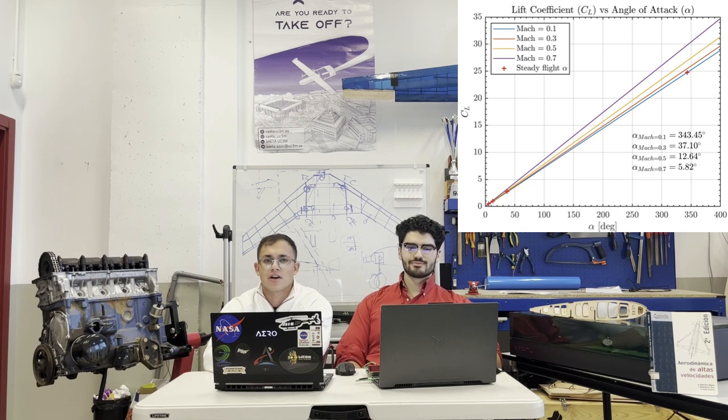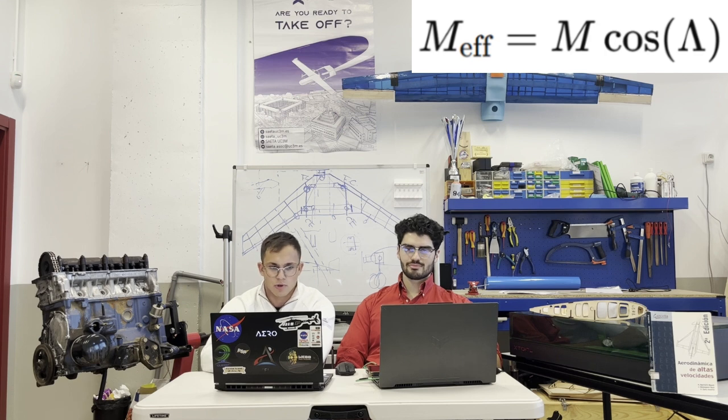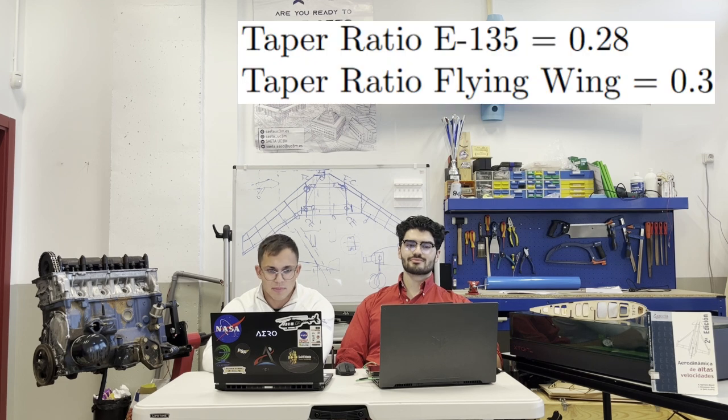Second, we should study the drag as a function of velocity instead of the drag coefficient, for this can be misleading. It can be shown to be minimum at Mach 0.63, as my colleague mentioned before. This result would have been much lower if the wing was not swept, because swept wings attain their maximum aerodynamic efficiency at higher Mach numbers than rectangular ones. In our potential compressible theory, this can be explained by the fact that CL max is reduced as the sweep increases. In reality, wave drag also requires engineers to sweep their transonic wings. The taper ratio has also been optimized to increase the lift-to-drag ratio at a Mach near cruise conditions. So modifying the taper ratio will lead to lower aerodynamic efficiency and therefore a higher minimum drag.